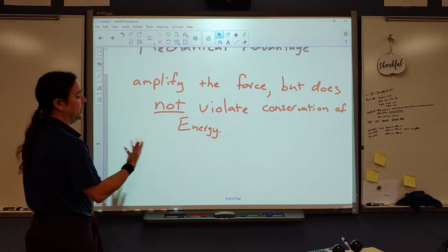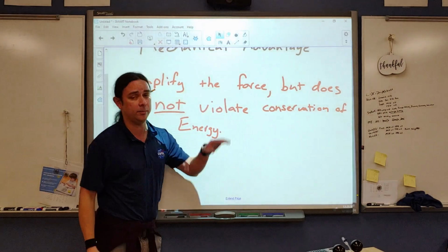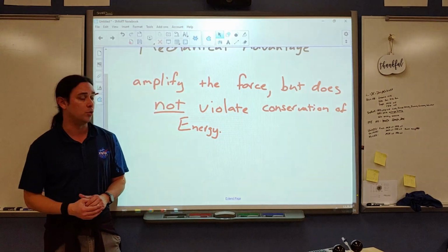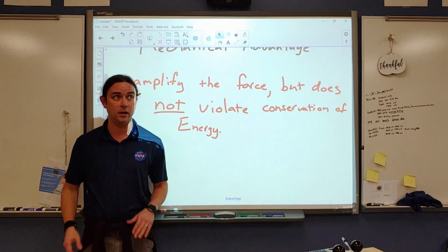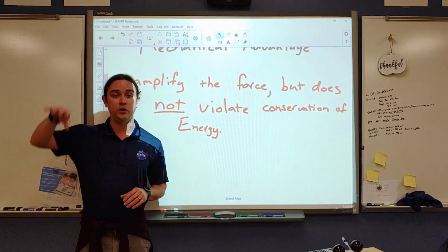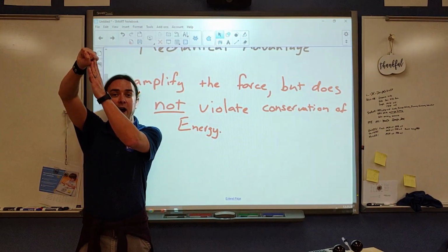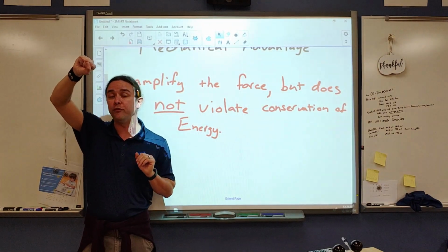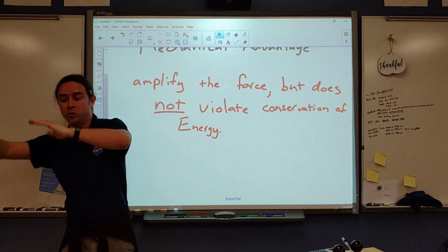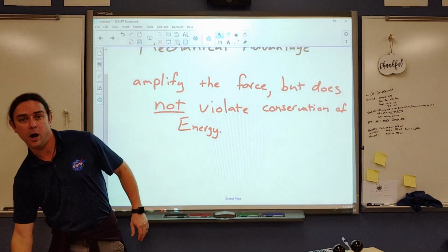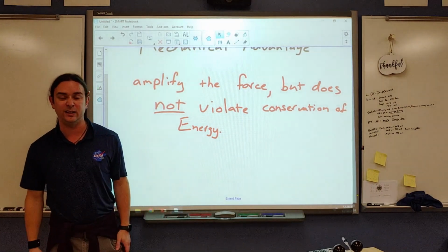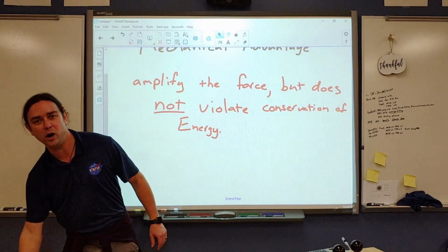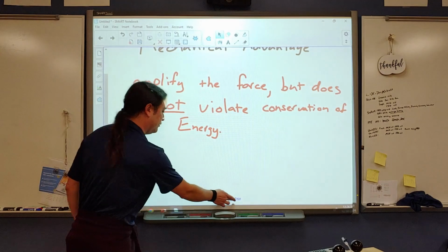But in this case, mechanical advantage, to reinforce this, does allow you to amplify the force. This is done many times with all sorts of things, including ramps and pulleys and other things. But you will find, just like we had with our example with the hydraulic lift for a car, if you have a very small force, think about how much you have to apply that over. Remember, energy deals with work or force applied over a displacement. So I take the handle up here and I push way down. I'm actually applying that small force over usually at least a meter. And does that result in the car being lifted up a meter? No. Usually when you do one of those, small force, big distance, in fact, let's take a look at that.